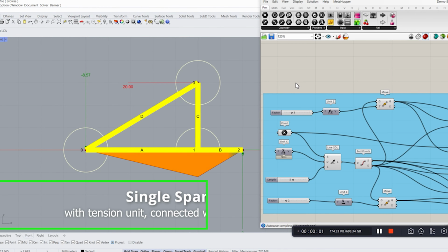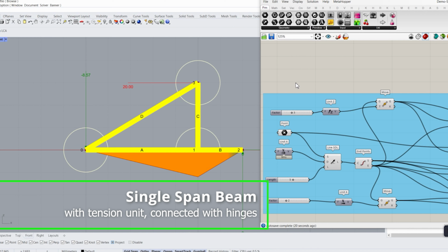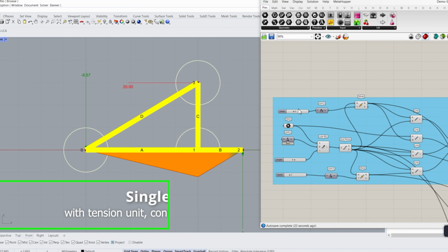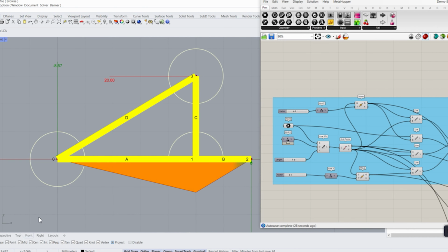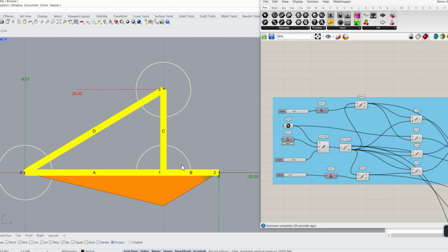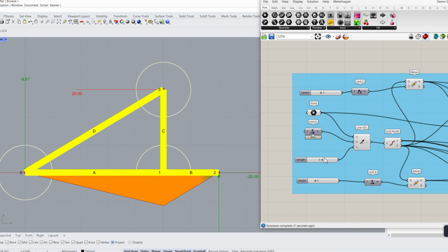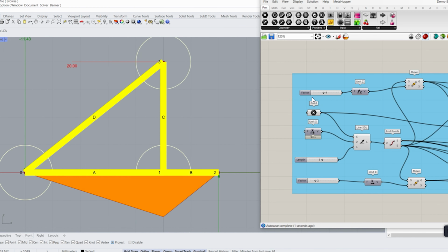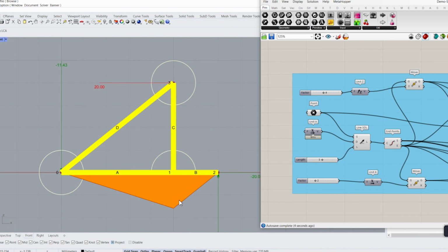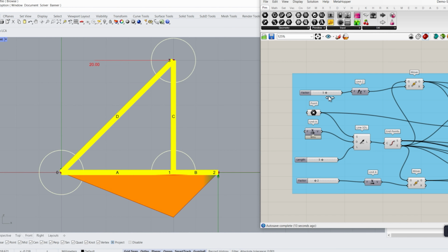Hi everyone, in this video I wanted to show you something different, this time with the plugin Karamba3d for Grasshopper. Let's see just a simple statical construction only in the XZ plane, with parametrical lines of the system at different distances, so we can explore the deformations, or like here, the moment diagram in y direction, and the utilization of the profiles